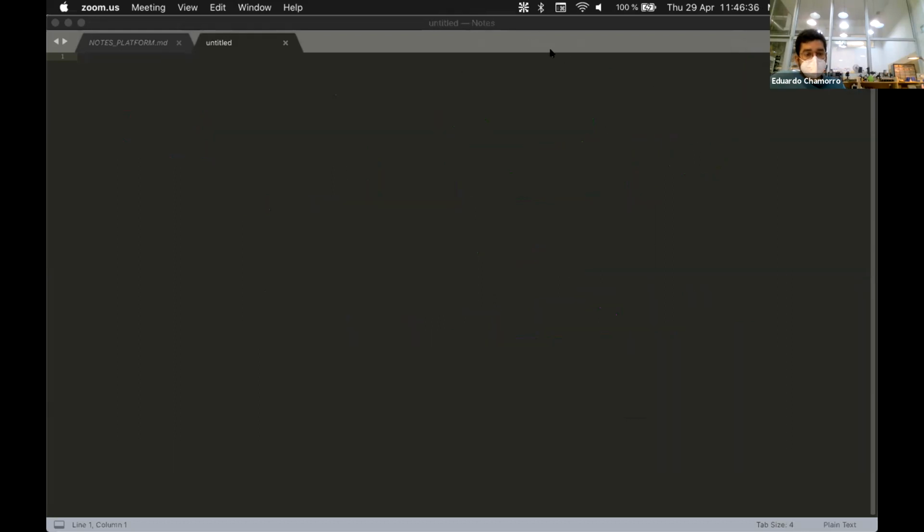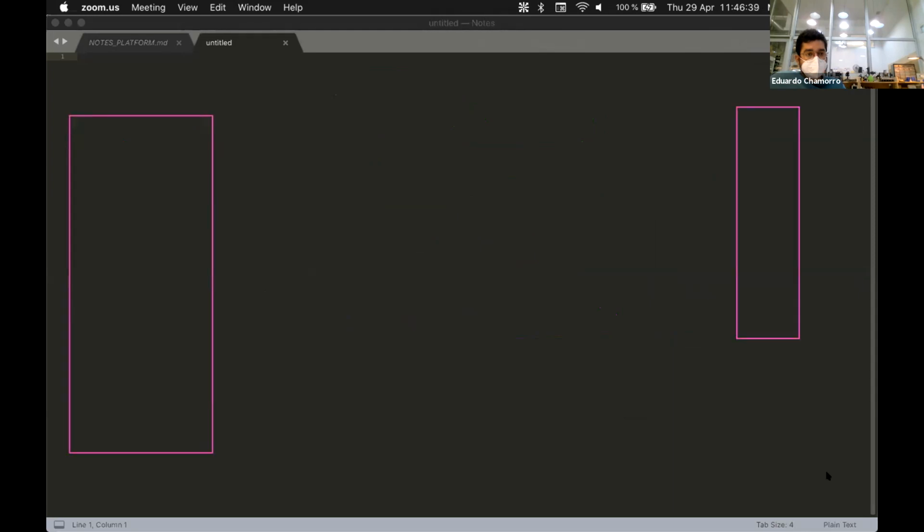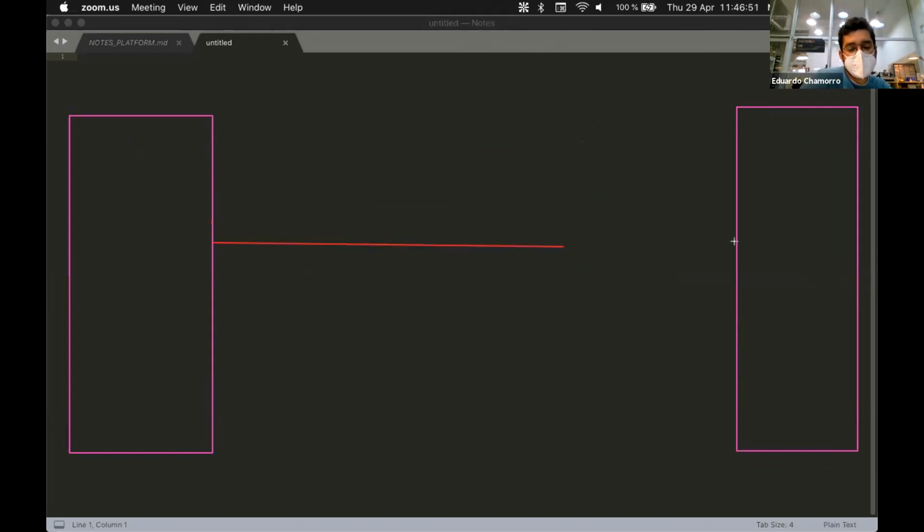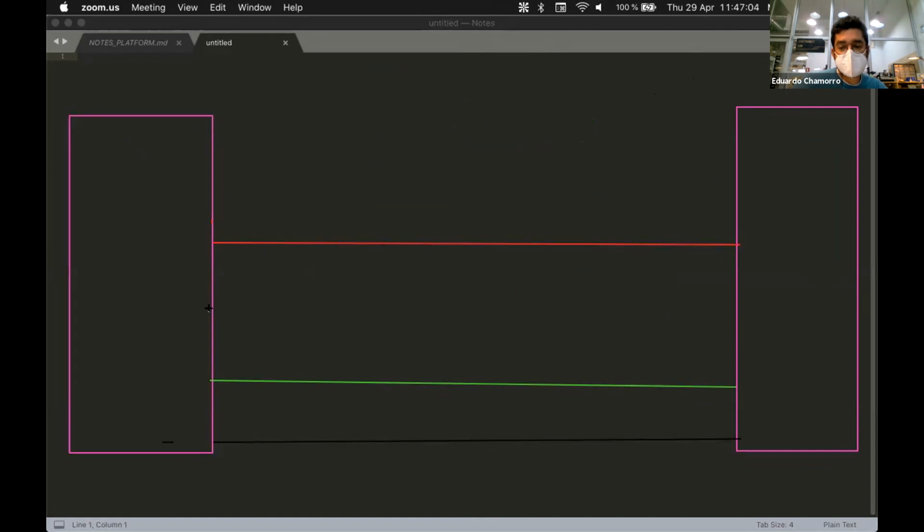And to simplify that very quickly, and stop talking because I'm talking too much: when you have the data lines, you have SDA and SCL, and then you have the famous pull-up resistors that pull the line to high, right? So these two are pull-up resistors.